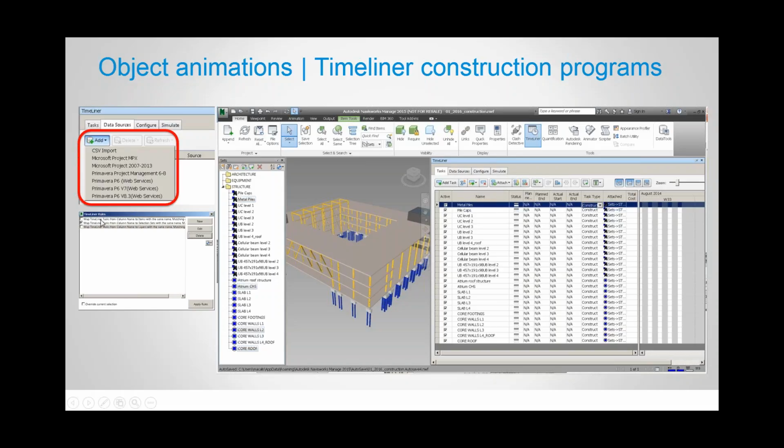So you go to Navisworks Timeliner Rules, and a little bit hard to see here on the left, but you can map the Timeliner column names to the selection sets. So that's what I've done. I've gone through and I've got my construction program. The names do have to match, so make sure you've got this in your BIM execution plan, that whatever you create here has to match the construction program.